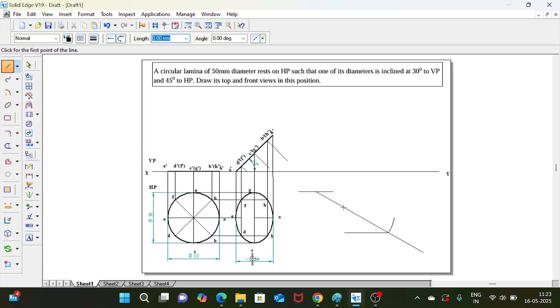Then you need to draw the second arc, which is 35.66. So move the cursor on the arc center, it will highlight. Okay, so now take the second arc dimension 35.66, press enter and draw the second arc from here to the locus. Okay, now join this line. The second arc intersecting at the locus to the arc center line, you need to join. Then measure the angle.